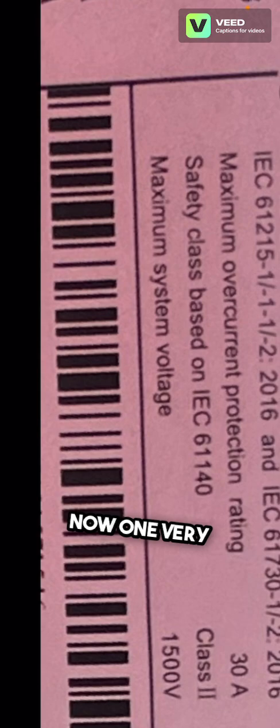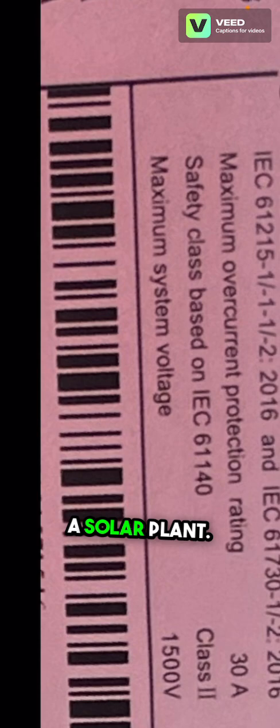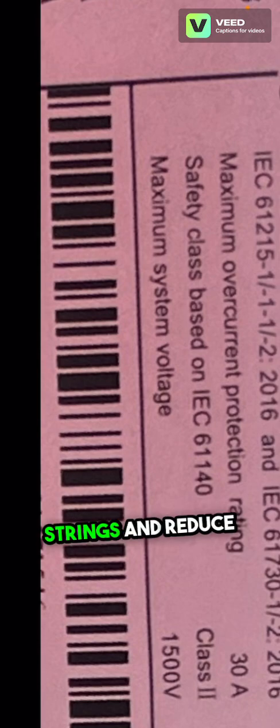Now one very important value is maximum system voltage. This tells us the maximum DC voltage this panel can safely handle in a solar plant. Because of the 1500 volts rating, we can connect more panels in one string and reduce overall cable losses.